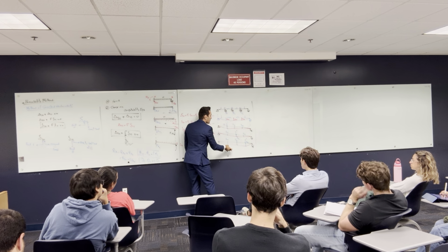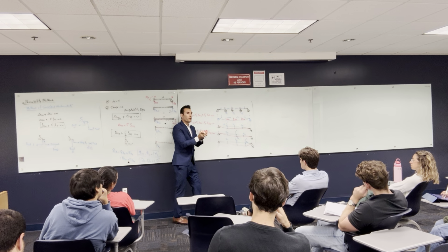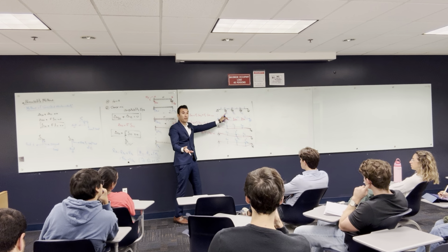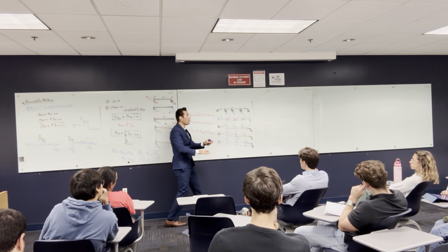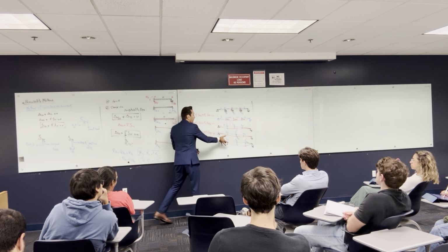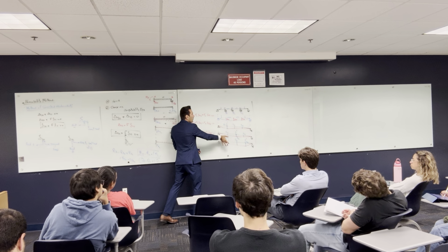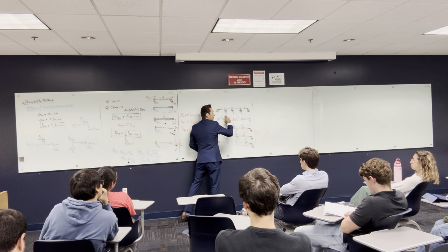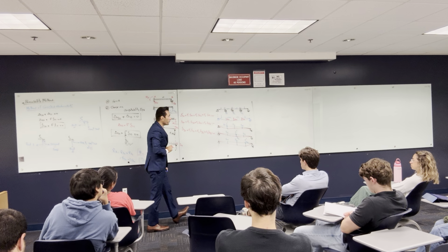All these deltas should at the end of the day make the deformation equal to 0. Why? Because there's a hinge here. There's no way that this point is going to move. So we are trying to manipulate the equation to find the forces that make a counter deformation that counters the value of the deformation that comes from the original load.